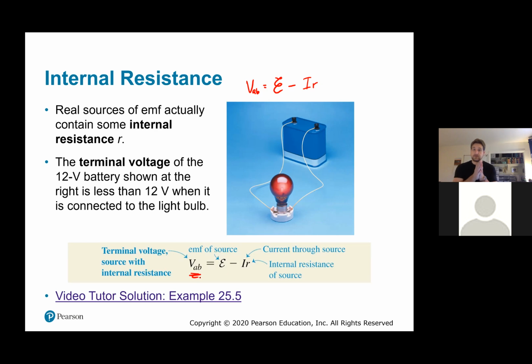If it's some kind of redox reaction, then there's a certain energy of reaction associated with that particular chemical reaction. There is a fixed amount of electromotive force. It is reduced on its way out by the internal resistance according to the current that we are pushing through.